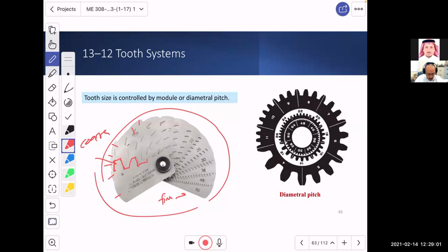You got that. The same goes with gearing. You can't just guess it. Look, this is a diametral pitch of 4. From this distance to this distance, you have 1, 2, and a half teeth. But if you look at a diametral pitch of 10, you have a little half here, then 1, 2, 3, and then half.